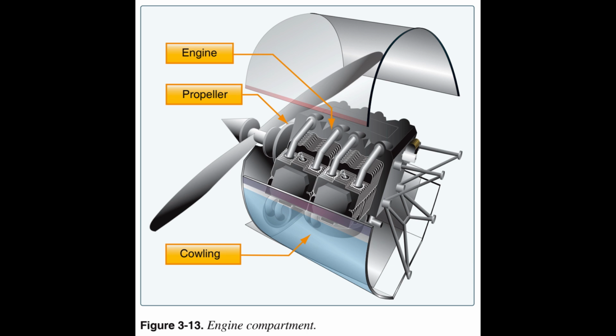A propeller is a rotating airfoil that produces thrust through aerodynamic action. A high-pressure area is formed at the back of the propeller's airfoil, and low pressure is produced at the face of the propeller, similar to the way lift is generated by an airfoil used as a lifting surface or wing. This pressure differential develops thrust from the propeller, which in turn pulls the airplane forward. Engines may be turned around to be pushers with the propeller at the rear.